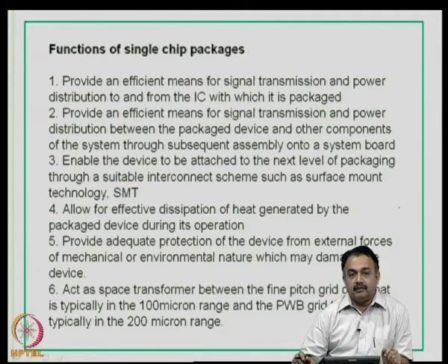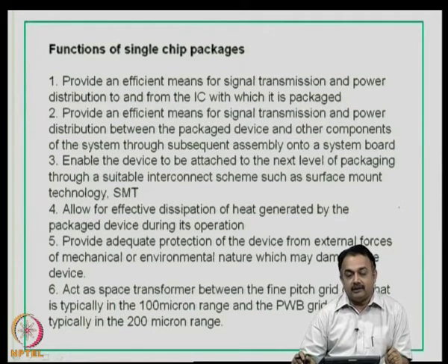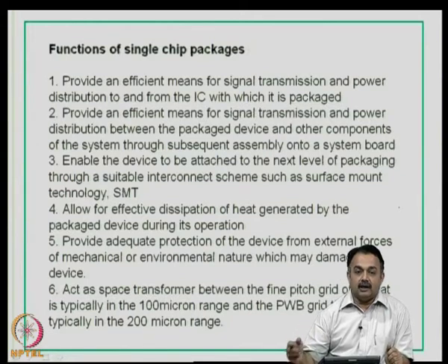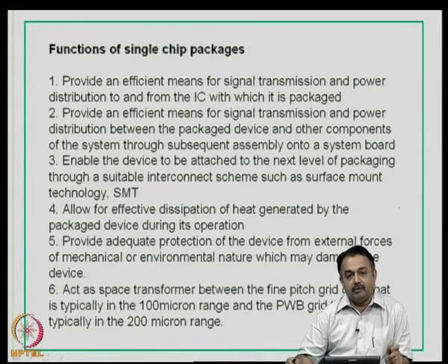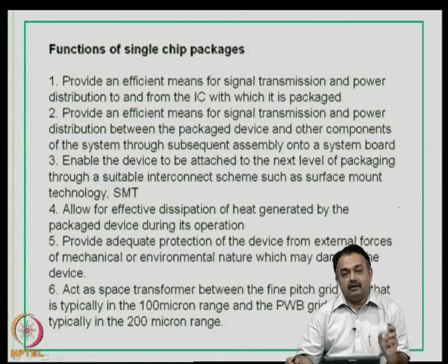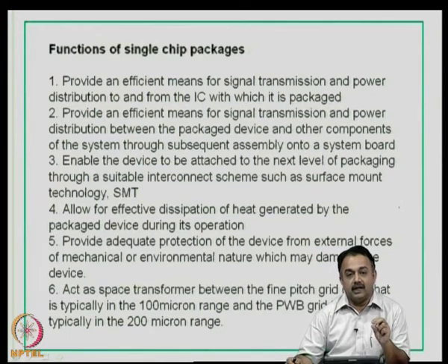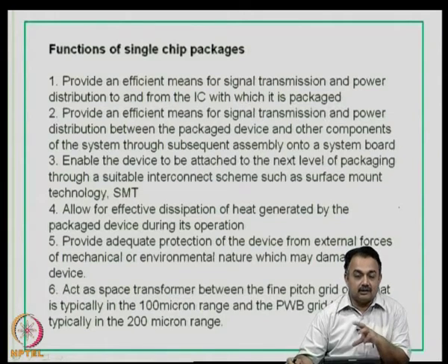Power distribution is very important for the working of the IC, and that depends on the power that you have calculated for running the IC without a package, and with the package you have to do some testing before these packages are sent to the market. These packages will have to provide an efficient means for signal transmission and power distribution between the packaged device and the other components that you are going to mount on the system level printed wiring board, because an IC is not going to perform by itself. The performance is related to the other subsystems.